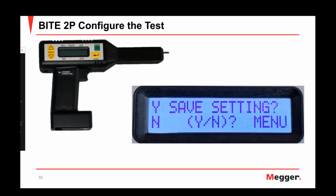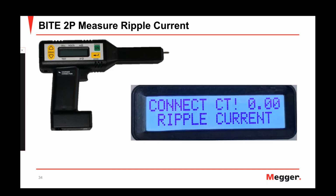The next screen is going to ask you to verify the settings to be able to start your test. Go ahead and press up for yes to start the test. If you press down for no, it's going to take you to the very beginning of the configuration process of the receiver. So it's good to keep that in mind, that you pay attention to what's going on whenever you're setting up the instrument. The very first measurement that the BITE 2P asks for is the ripple current measurement.